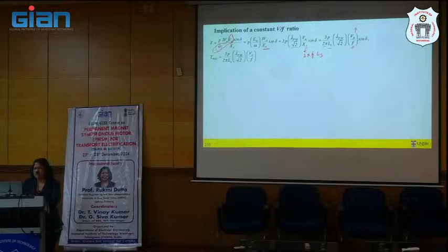EA over omega is your magnet flux linkage, equal to the magnet flux linkage in the RMS value. So lambda PM is your peak value, that's why lambda PM over root 2. And VA over XS, this part, we can also write as VA over 2 pi f Ls, and VA over f, this ratio.